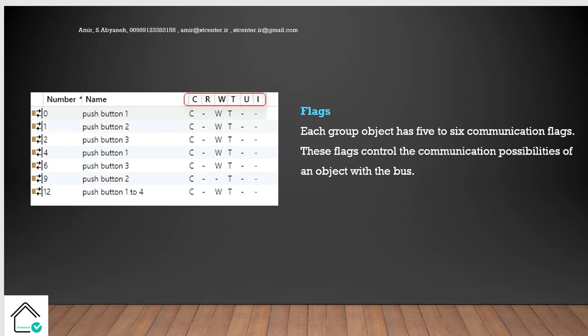But sometimes the manual of a device mentions changing the flag in specific circumstances, or if you want, for example, to configure new devices with old devices, maybe you need to change the flags. So keep this in mind. It's not a regular job to change the flags in KNX.